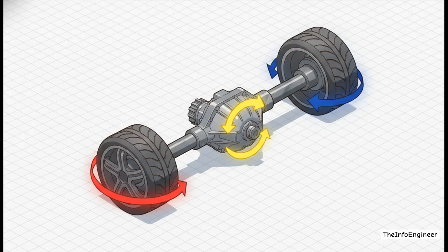There's no cheating it. If your carrier is spinning at 100 RPM and you take a really tight turn that slows the inside wheel down to 90 RPM, the planetary geometry dictates that the outside wheel must speed up to exactly 110 RPM. The speeds diverge, but they always average out to the input.